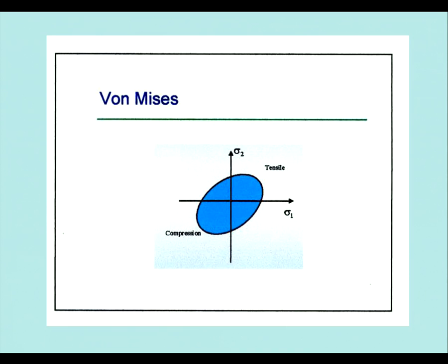I'm going to generate a hoop stress so that I can have a stress up here which is equivalent to the hoop stress. But I'm going to get a longitudinal component of it, which is the hoop stress times Poisson's ratio. So I've got a line that comes up in here.